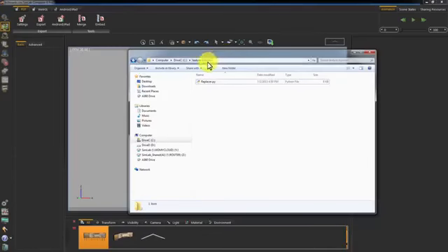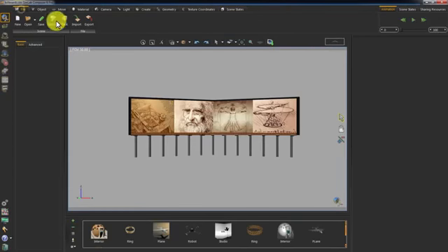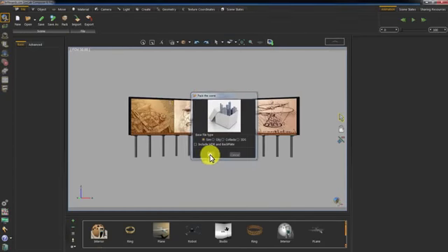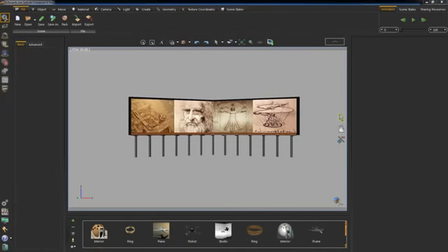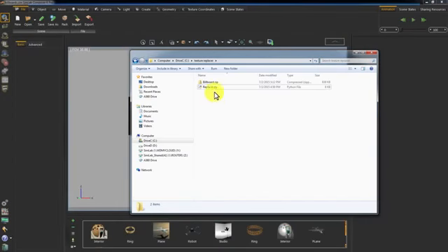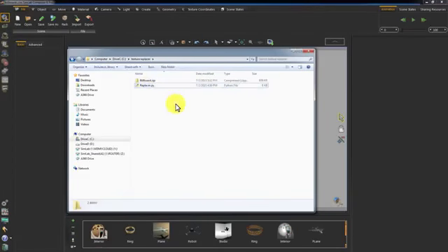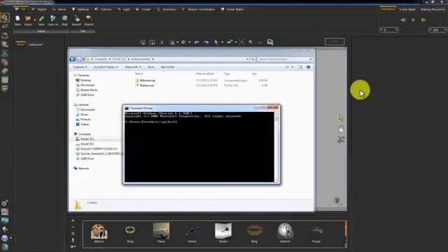I created a folder and named it Texture Replacer and put the Python script inside it. Go to SimLab Composer and pack the scene to include all the data related to it. This is a very important step. Now that we packed the scene, we will open the Windows command prompt to run the script. Type the path where you installed the Python to run Python, followed by the location of where you placed the script, and press Enter on your keyboard.